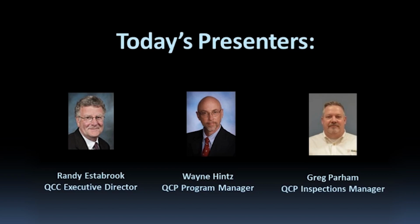You know, it may actually blow your product apart if you're going across 2 moisture zones, if you know what I'm saying. So we try to keep ours in the middle, so if we have to go high or we have to go low, we're safe either way. I think that's a good practice. I don't know how many people actually check or monitor the relative humidity in their plants, but I think your target, that 35 to 45 range, is probably a very good target to try and maintain. Yeah, and then when it goes below 25, we have to say something, or if it goes above 55.